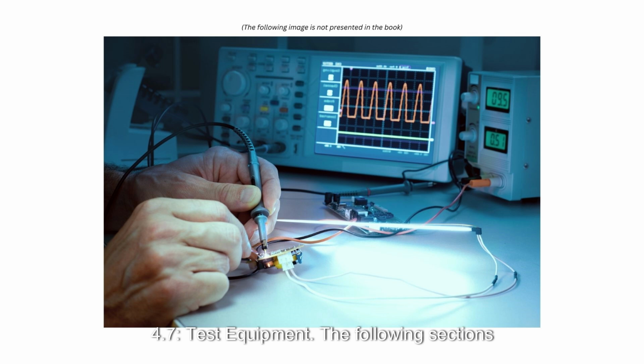4.7. Test equipment. The following sections will focus on the test equipment more commonly found in the fabrication and assembly houses, rather than the design labs. 4.7.1. In-circuit test, ICT. ICT, in-circuit test, relies upon the use of probes to make contact to the metal on the printed circuit boards. ICT testers can be programmed to perform the entire test mentioned in the previous section, plus some. There are two connection methods commonly used in ICT equipment, known as bed of nails and flying probe.